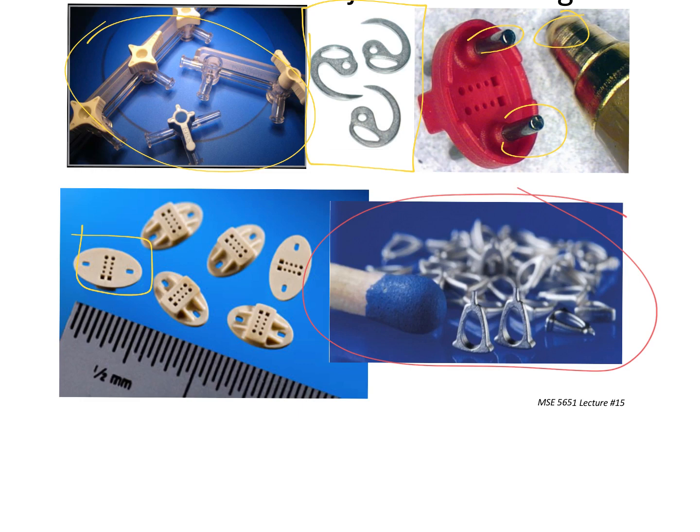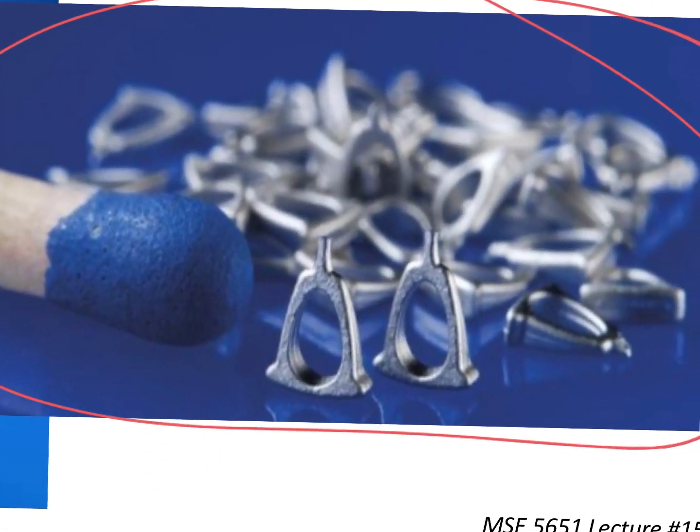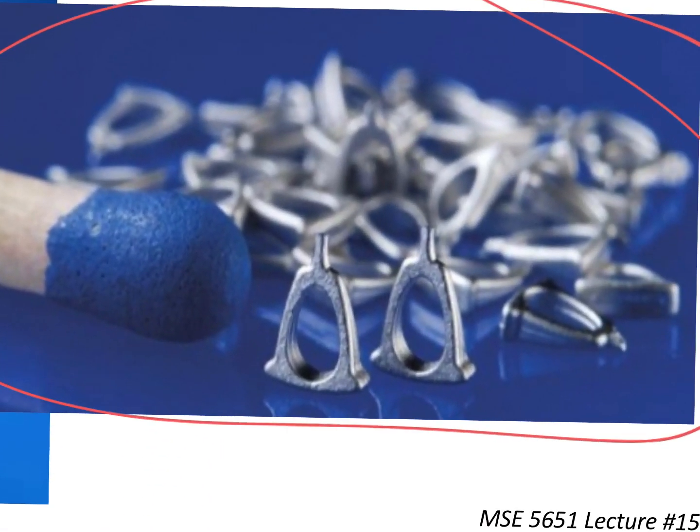And the issue here is that all of this is really small, okay? These dimensions obviously are pretty tiny, and if you take that stirrup and cut it in half, you'll see you've got maybe 100 microns tops from one edge to the other. That means everything we were talking about becomes even more important, because if you have a 100 micron span in that tiny part, you can't have a 100 micron grain, all right? That's a disaster. That's a huge weak link in that structure.